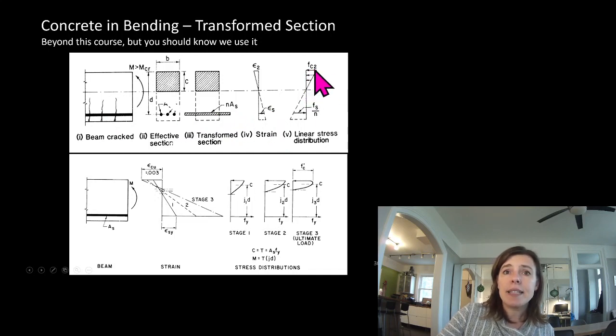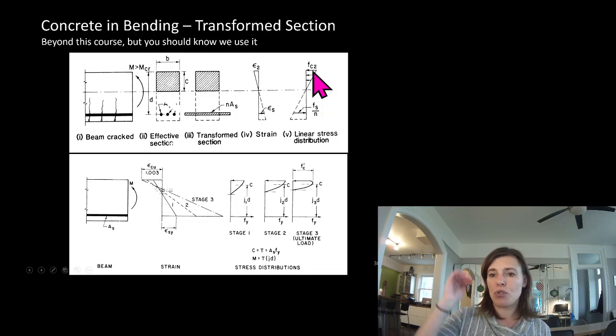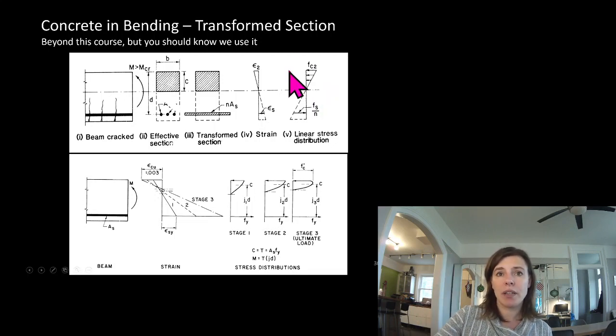And this is the stress in the concrete portion, and right here is where the concrete would fail, where the extreme fiber of our brittle material would, if f_c hits our f'_c, or that maximum value of compressive strength for our concrete, it fails. And this is the stress in this portion, which we've represented as actually the force in the steel, which is a ratio of its area, or its stress related to its area.